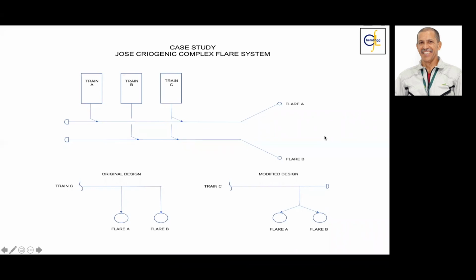In the case of ground flare, it is a little bit easier because the ground flare is divided into sub burners. You have a main header that is the inlet, but you have several burners, and when you purchase the ground flare, you purchase it with spares, or with places to allocate another subheader for burners.